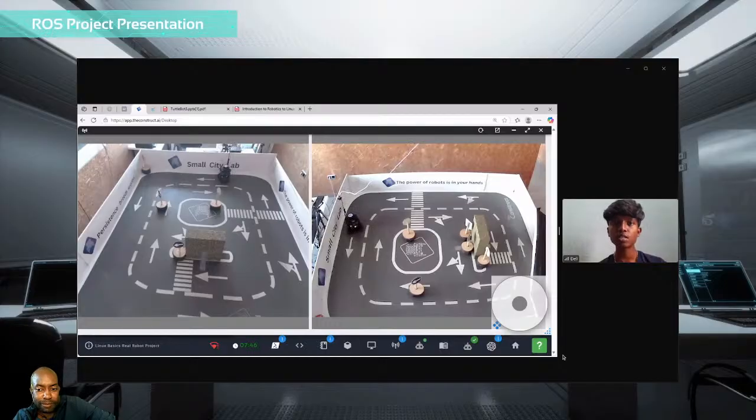Yes, I should change the angular velocity. Maybe not exactly. You should probably check the obstacles in front of it more often, because once it's clear, there's no need for it to keep rotating, right? Okay, sir. You see, right there was nothing in front of it, but it kept rotating. So when you are taking in the laser scan data, there is something you are doing excessively. For example, it turns 180 degrees out of the way when 90 degrees could just do, right?